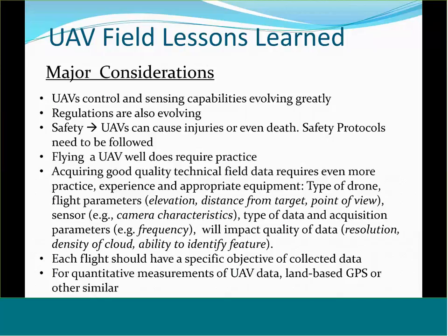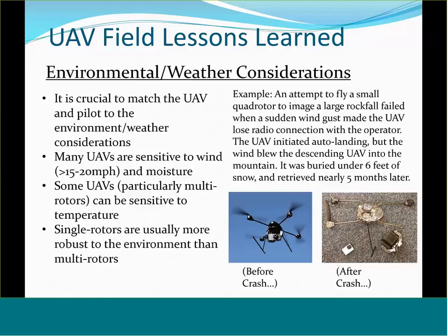If you want to get quantitative measurements from the UAV data, we strongly recommend the use of land-based ground control points with GPS or other similar surveying equipment, because they can correct your model, improve the accuracy, and ultimately improve the measurements that you're going to be making from that model.